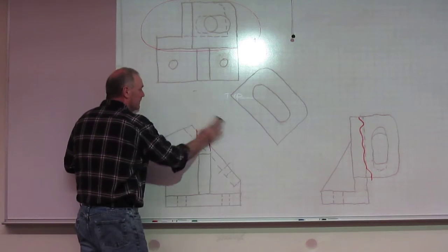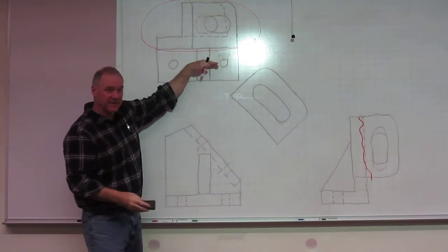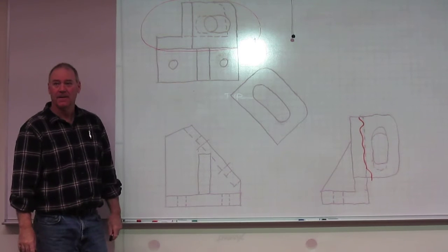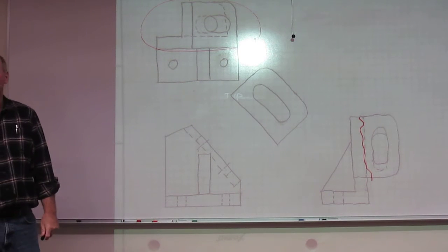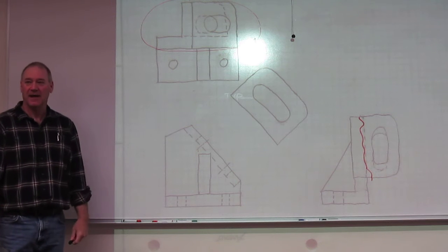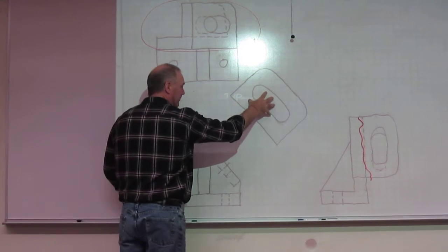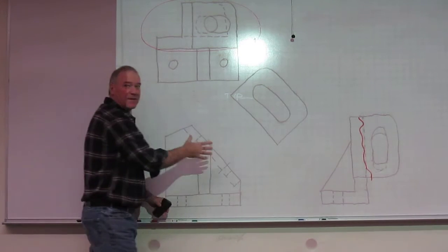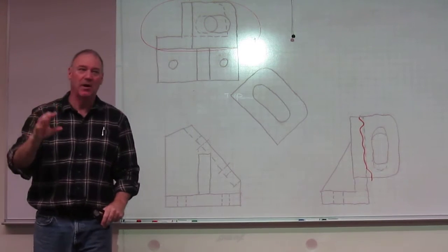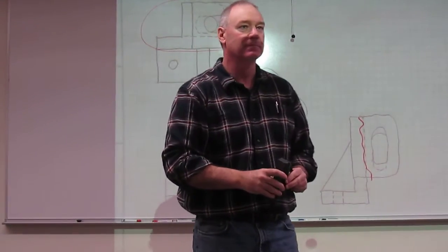Now there's another thing. So you go ahead and produce this. Is this thing getting in the way of this? Your spacing is going to be something you're going to want to look at fairly closely. Now the nice part about doing this on CAD is you can move things around, but keep in mind, if you're going to pull an auxiliary view like this, it should be lined up in that fashion so that somebody can make that rotation in their mind. So you're aiding them in the rotation.